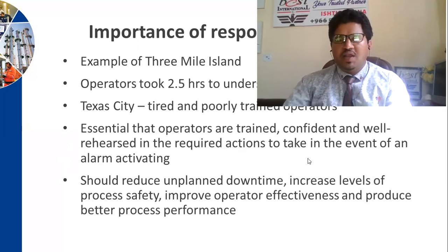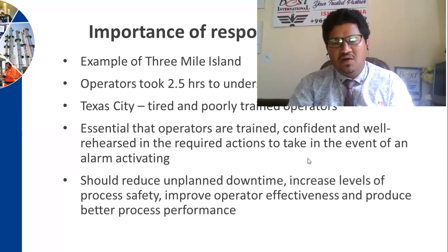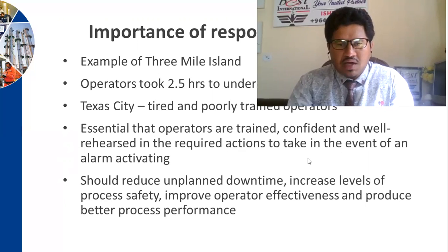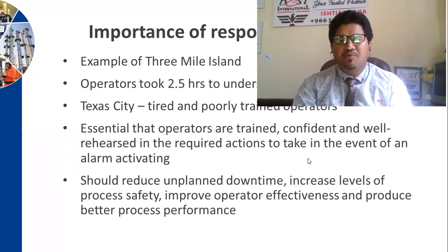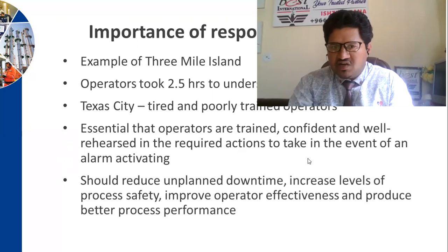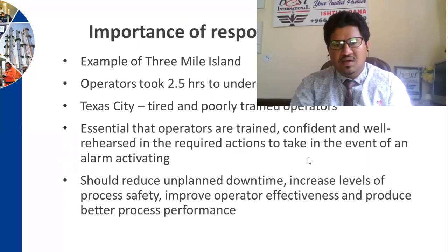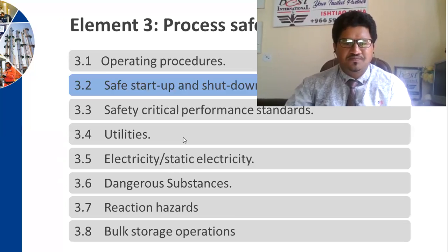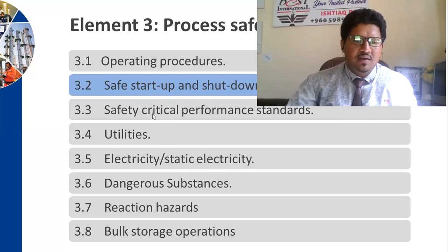So wherever human capital is involved, make sure they are well informed, well trained, knowledgeable, and technically sound, that the SOP is well understood, they know each step of the process, they understand the process deviation, they understand the process parameters, and they understand the SOE, the safe operating envelope, which they need to follow or play within.